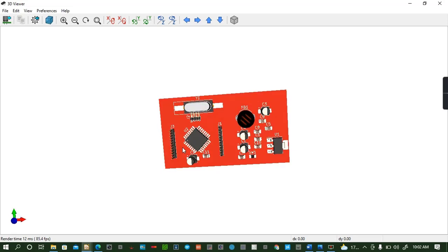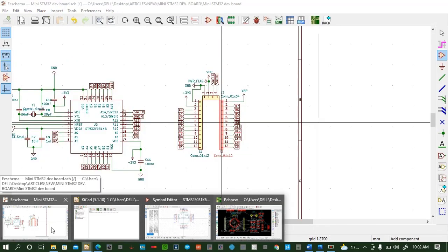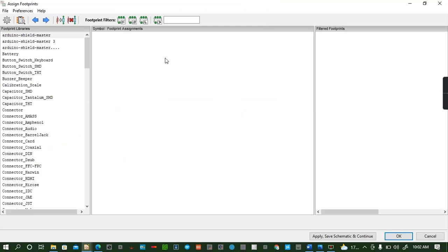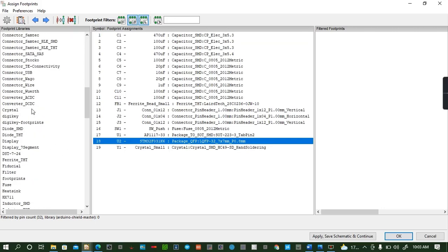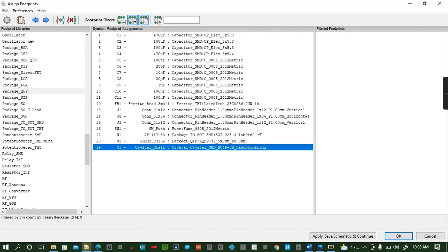Okay, I can change this footprint. It is too big. I want to change the footprint. That footprint is too big for my system. I don't like it. I want to make it a bit smaller. That is for the crystal quartz. Okay, that one is too big. For this package 7x7, I'm going to go to packages first. We have 5. Then crystal quartz. We got crystal.